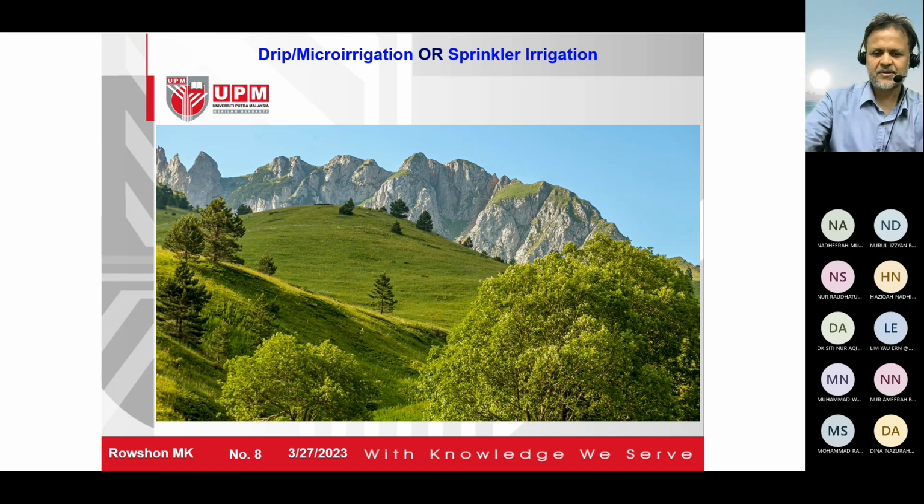Yes, this is micro, because of the sprinkler irrigation system, as I mentioned, there are two reasons. Micro irrigation system, I said, is low pressure, then low flow rate. Low flow rate means low Q, low discharge. And sprinkler irrigation is high pressure, and Q is also high.